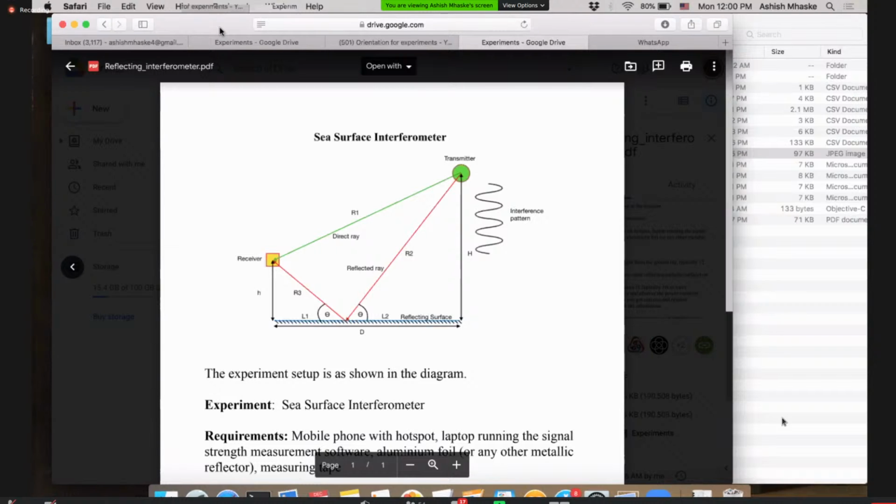So in order to avoid a prominent role of those kinds of reflections in your experiments, which are meant for studying something else, it is recommended that you keep both your transmitter and receiver at a certain height, so that there is no prominent reflection and the direct path power dominates.